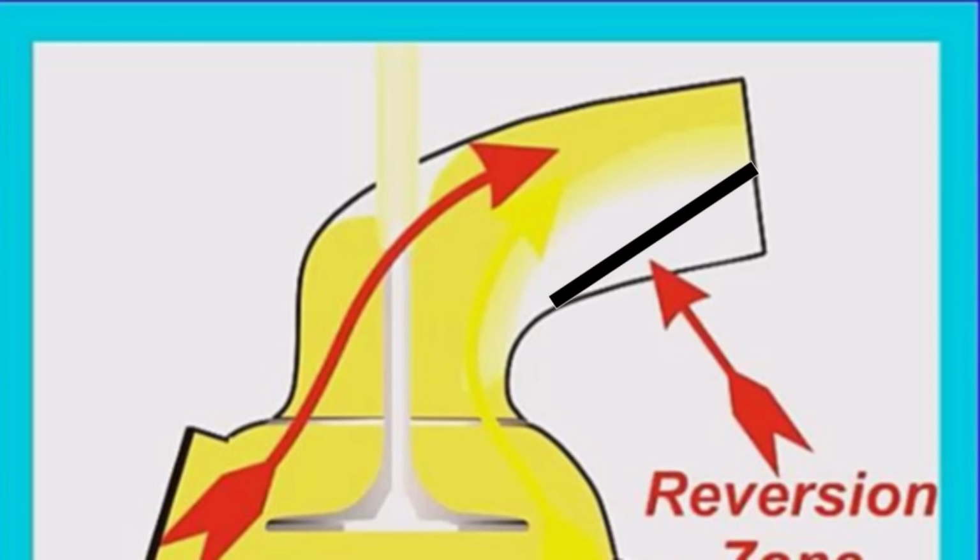In fact, the way to size something like this would be to put a plate in, as I'm showing here, and then tweak it until you just see a slight drop in flow, and then drop it down just a tad more. That will get you a port which flows just as good outwards as it did before.